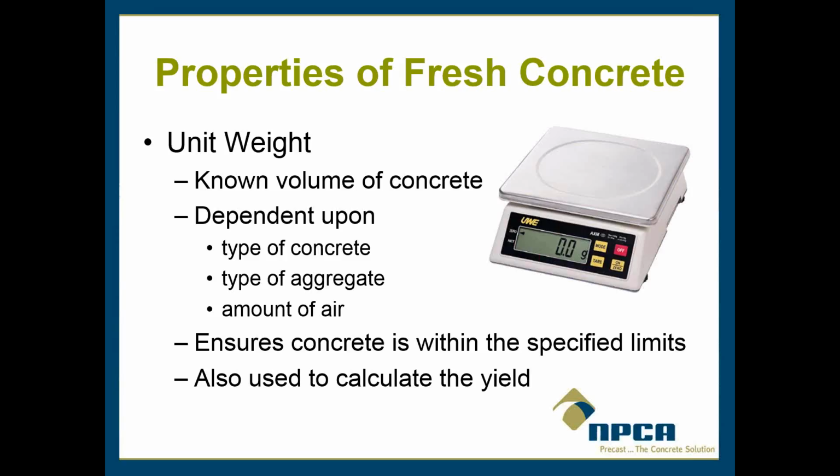Okay, next up is unit weight. This is determined by using your bucket, which is a known volume, and following the appropriate procedures according to ASTM C138 for filling the bucket and consolidating everything. And this is used later on when we calculate the yield.